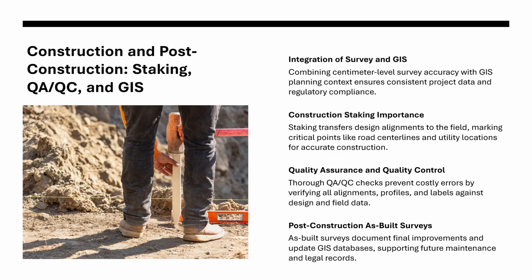And then finally, in the post-construction phase, the surveyor performs an as-built survey. These confirm that what was designed is what was built, documenting the location, elevation, and dimensions of improvements. As-built surveys not only close out the construction project, but also update GIS systems, legal records, and future maintenance plans.